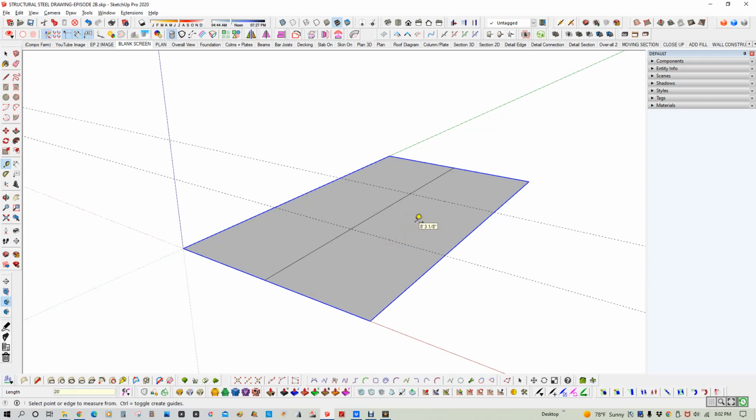A lot of different ways to do this. It's simple enough this way. I'm just going to go ahead and draw lines over these guidelines. So that gives me my 20 foot by 16 foot grid. So 20 feet this way, 16 feet this way. It's always good to measure from a corner, and you can go out different ways so you can check your dimensions quickly just by moving the mouse around to different points.